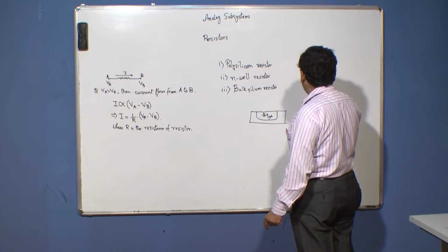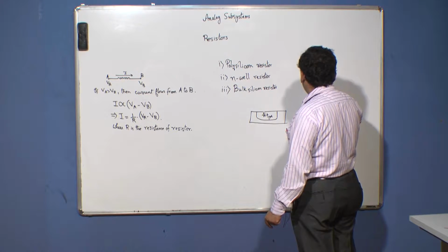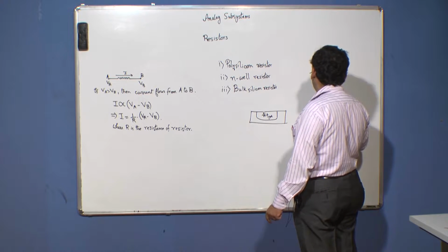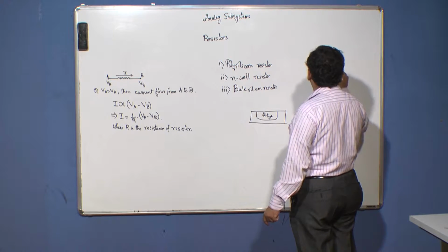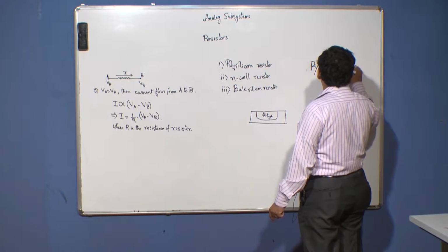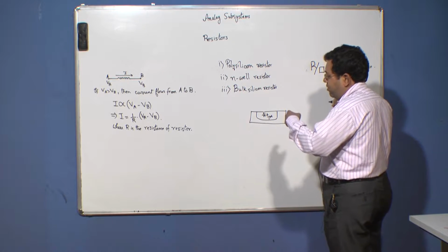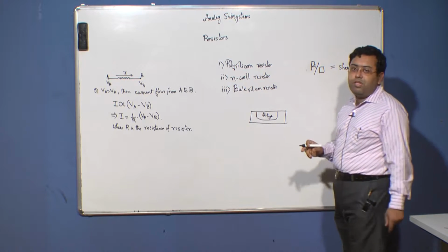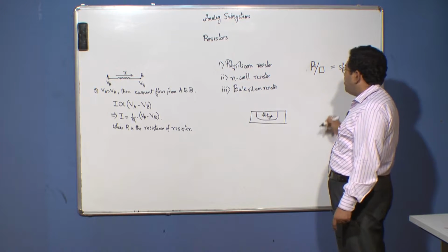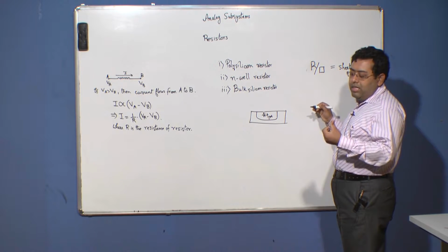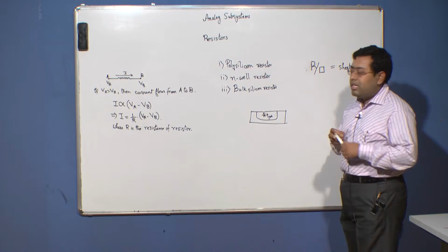Just for the sake of knowing, for all these resistances we typically specify the resistivity per square, or resistance per square, which is called the sheet resistance of the material, and you specify the area of your resistor as an integral number of squares. Each square has a unit dimension, and the dimension of your resistance is specified by the integral number of these unit squares, which gives us the amount of resistance we are going to implement in the circuit.